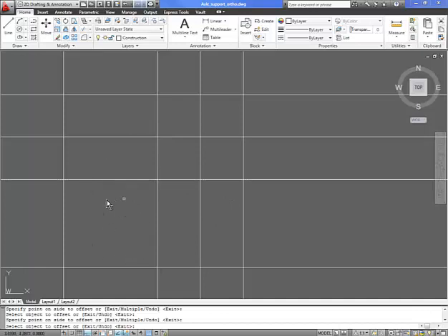So this will be our front view, this will be our top view, and this one will be our right hand side view. Now that we are there, we can draw a line right now, a miter line, to get information later on. So this will be our construction grid. All those are the bounding rectangles: front view, top view, and right hand side view.